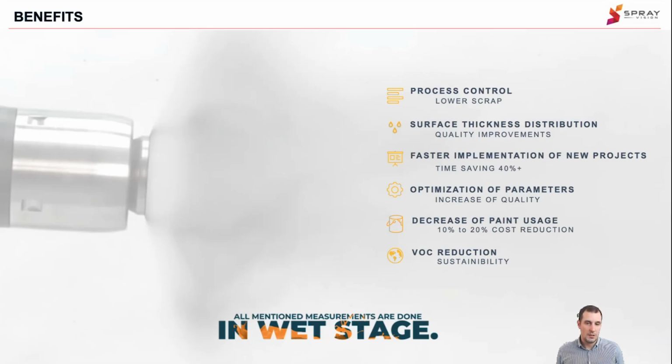I will maybe just sum it up. SprayCapture works on the transmission of light through the painted sample. You can do the measurement and control the output all in the wet stage, which is a significant advantage. You do not need to wait hours, but you have feedback about the result and its real dry thickness in a couple of minutes after you spray it.